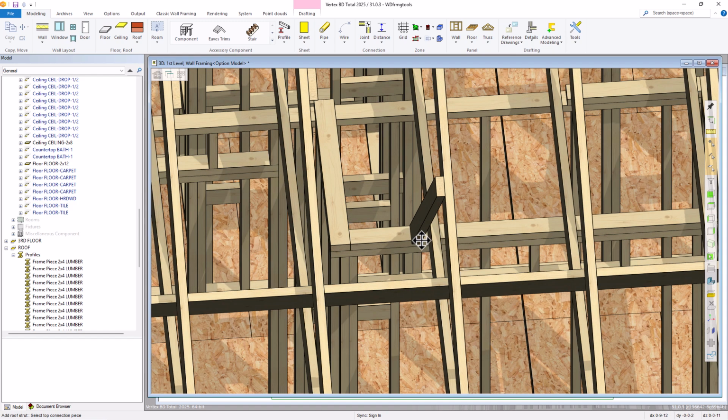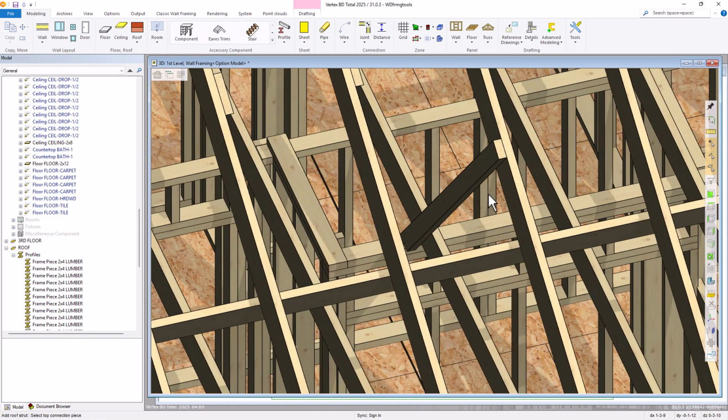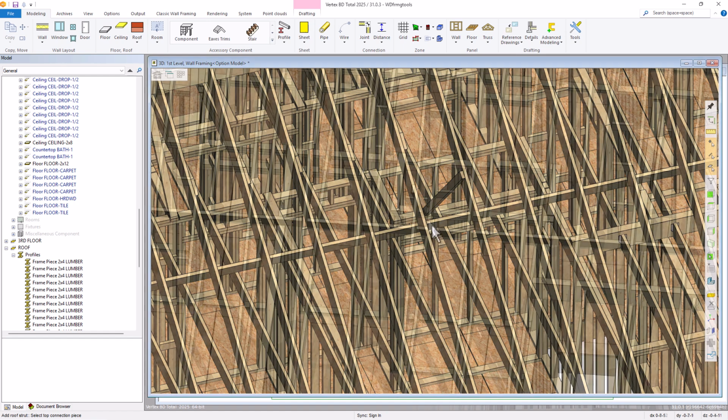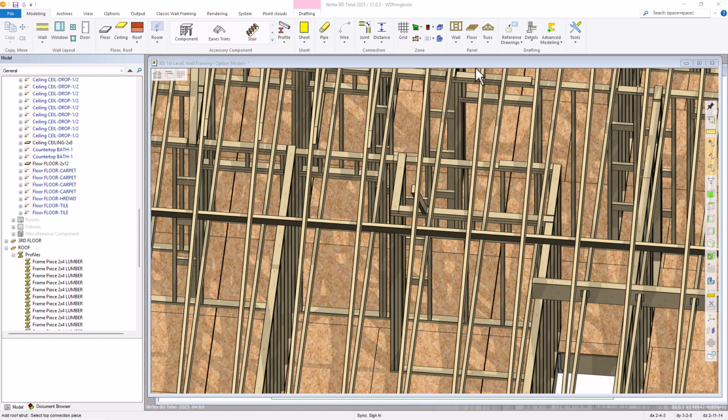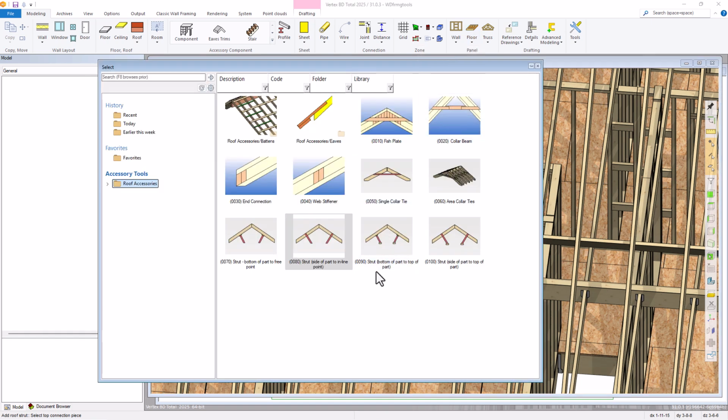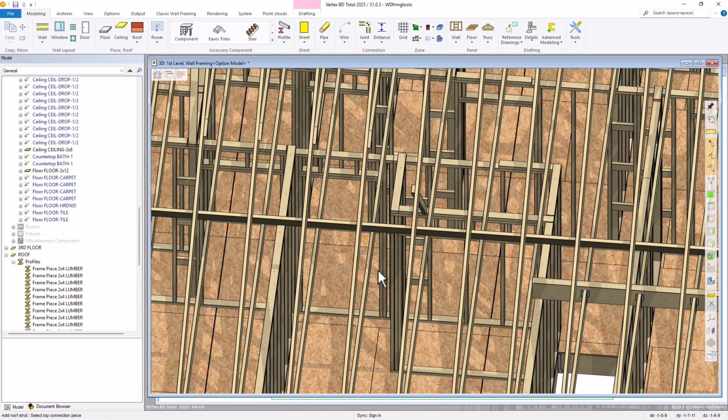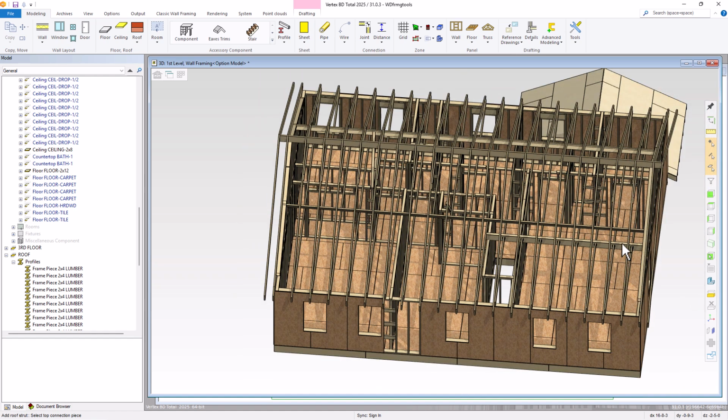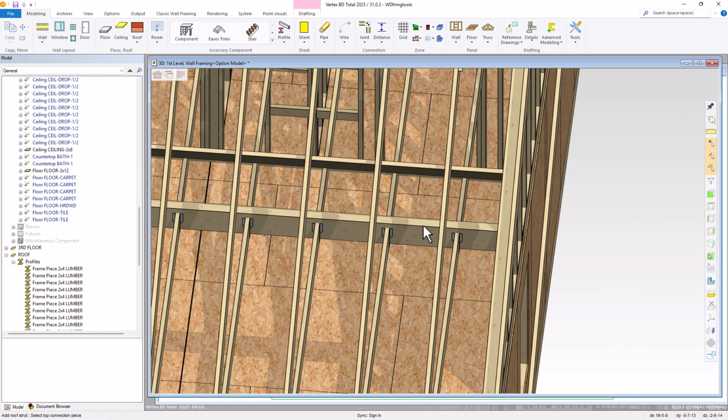The strut is added to the side of the rafter for support. The strut bears on the wall below while maintaining an inline angle. Another tool for creating struts is designed to connect the bottom of one part to the top of another. This accessory allows the user to place a strut under a supported part, which can bear on top of another part at any angle. In this example, I will add a strut to support the purlin, with the bearing end resting on the beam below.